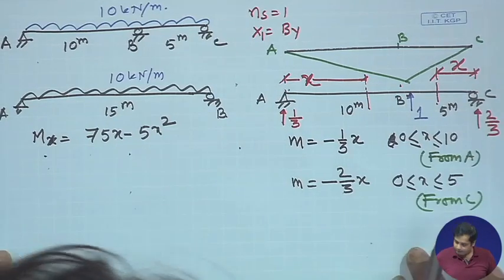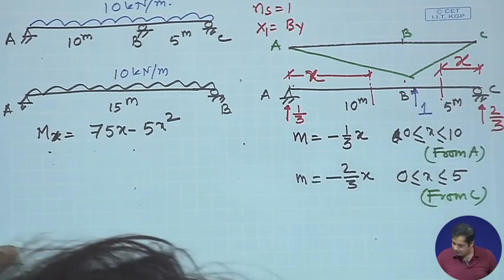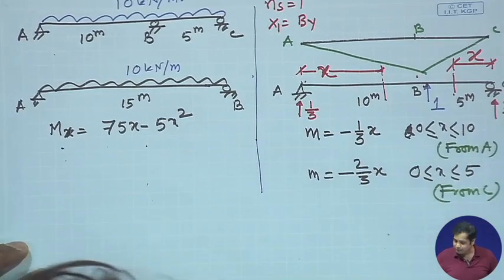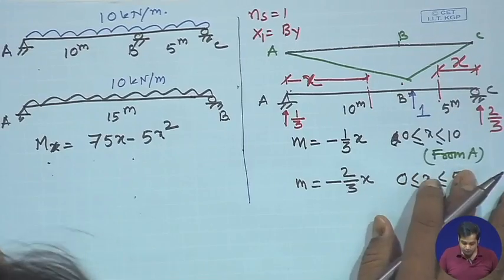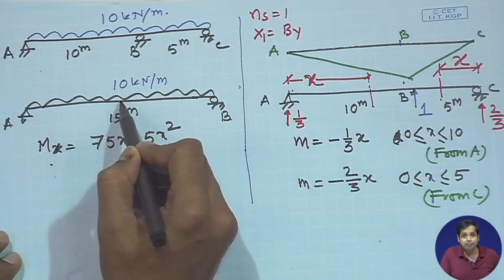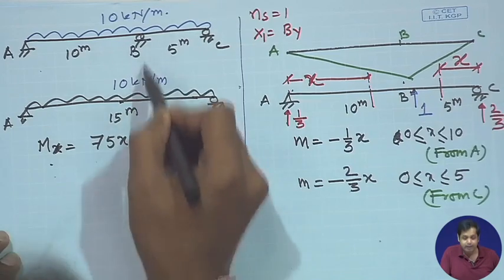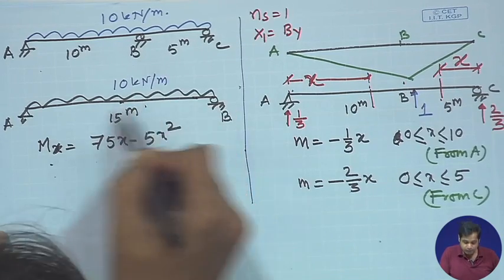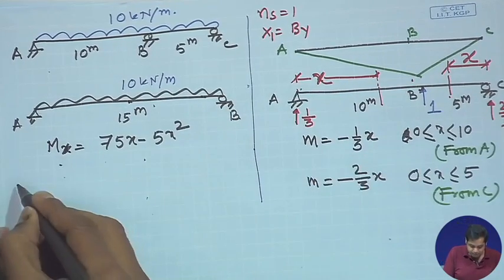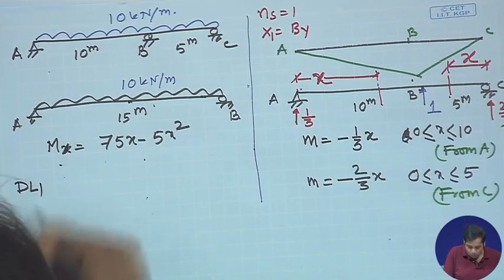Okay. Now, great. So, once we have this, next step is we need to solve it, right. We need to find out the vertical displacement at point B due to this externally applied load, and suppose that displacement is equal to dl1.